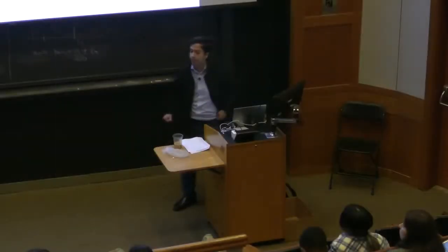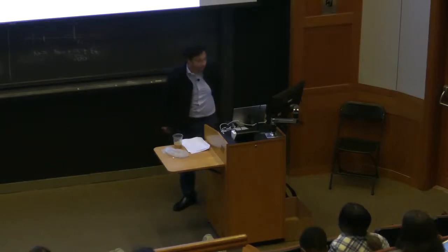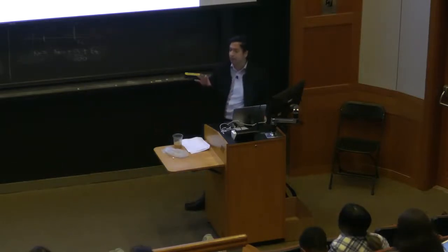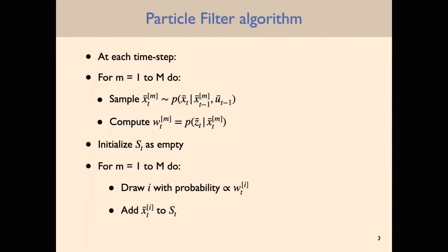Yes? So, is the robot given a map of the world before? Okay, good question. Yeah, so right now we're just focusing on the state estimation question. So in this context, it's called localization. So the robot just wants to figure out its x, y, and theta. So we are assuming that it has a map of the environment. We'll relax that assumption in about 2 lectures, but at least for now, it's just the state of the robot itself that it doesn't know.